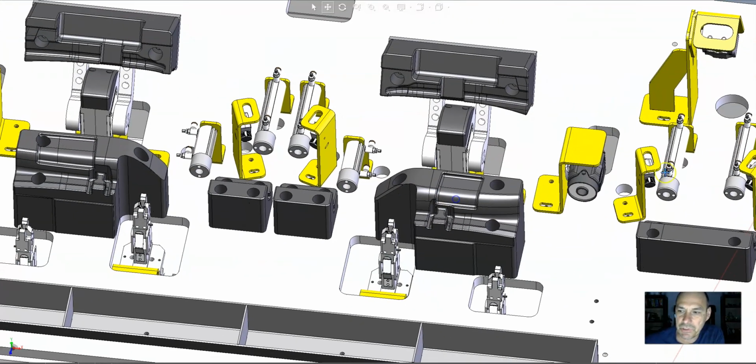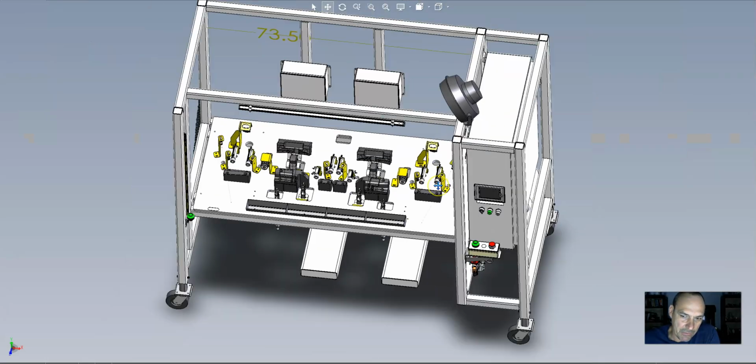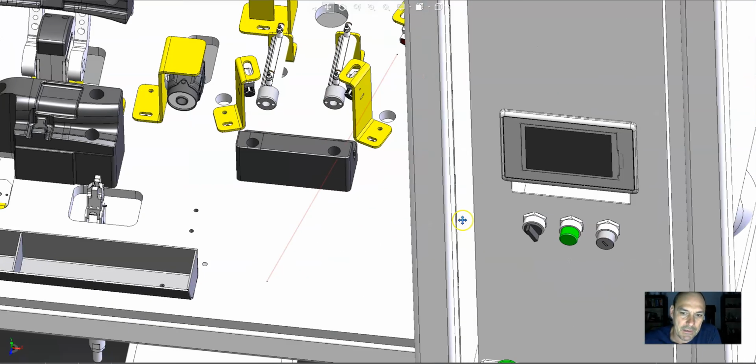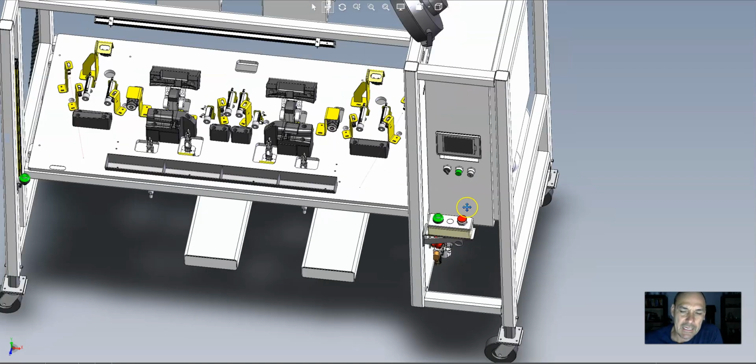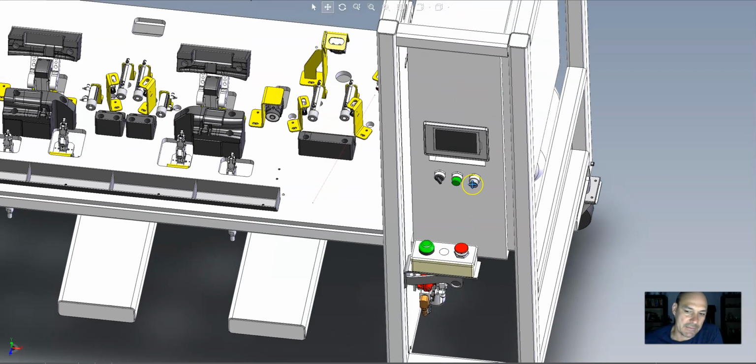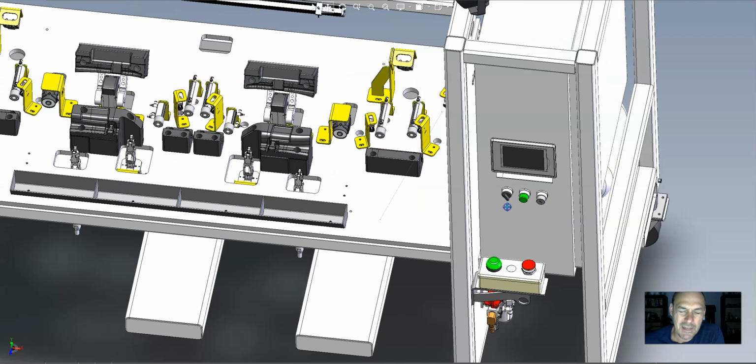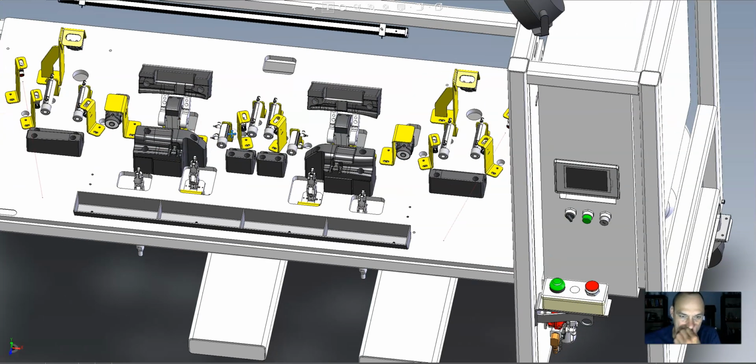And I've got lasers. I'm going to be very interested in what's going on up here, because what do I need to do? I need to walk around virtually, or literally walk around the machine, and get a list of all my I/O, right? That's what we'll start with. In my case, I had nothing but this drawing to develop the electrical prints that the electrician would use to build the control panels. So I had to get all the I/O and write it all out, and then I would know.